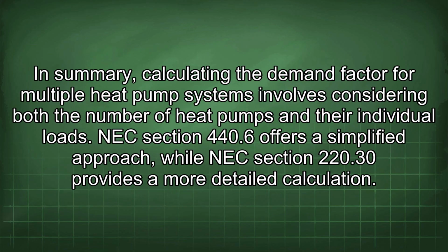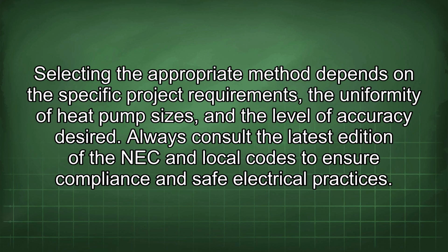In summary, calculating the demand factor for multiple heat pump systems involves considering both the number of heat pumps and their individual loads. NEC section 440.6 offers a simplified approach, while NEC section 220.30 provides a more detailed calculation. Selecting the appropriate method depends on the specific project requirements, the uniformity of heat pump sizes, and the level of accuracy desired. Always consult the latest edition of the NEC and local codes to ensure compliance and safe electrical practices.